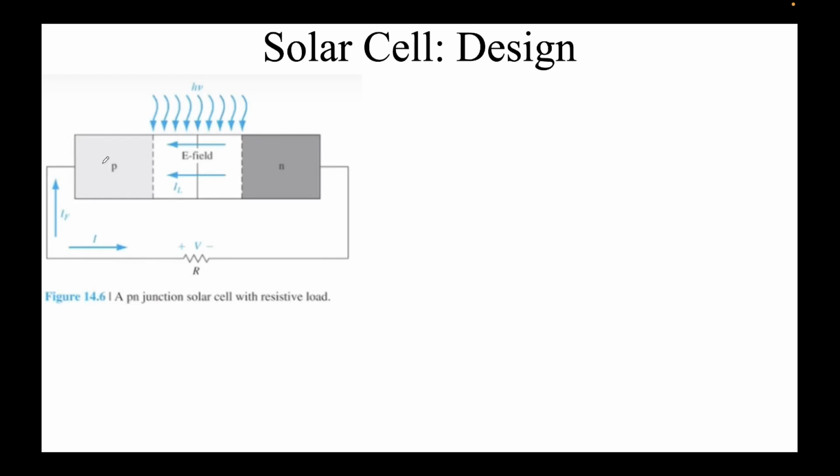So one way to do this is to just reduce the thickness of the P side. Let me draw the very first design. So this is your P, and remember again these are epitaxially grown, so this is my direction of growth. That part always remains, please remember that. So this is my n-type material, this is my p-type material, and there will be some depletion region.